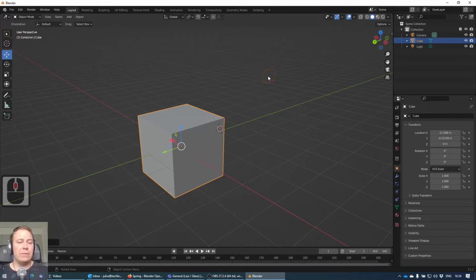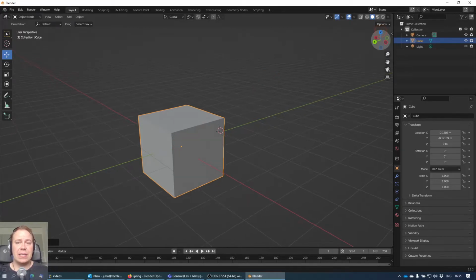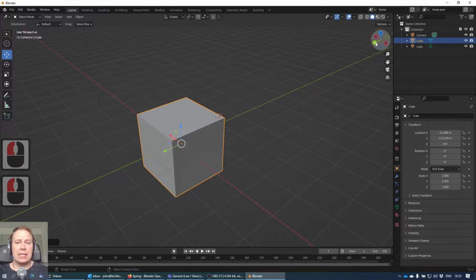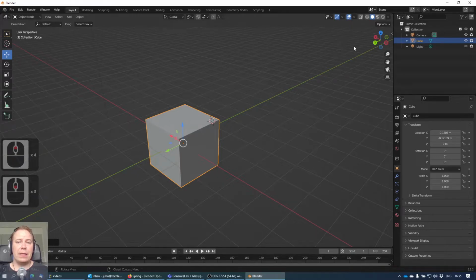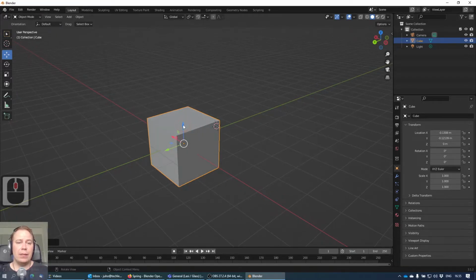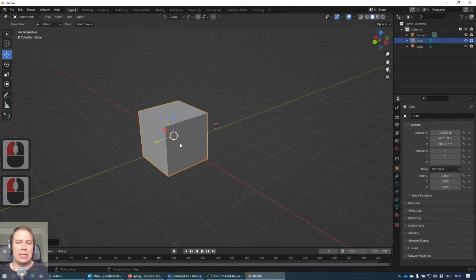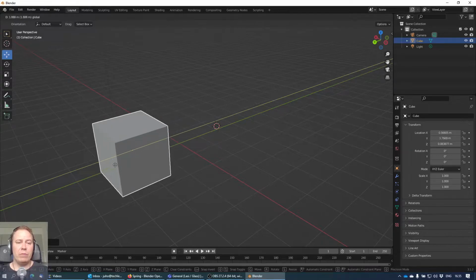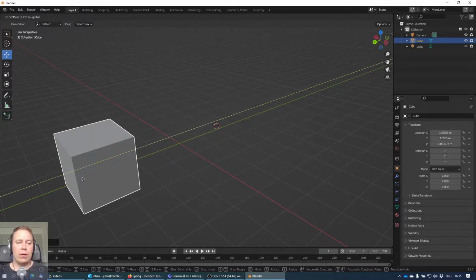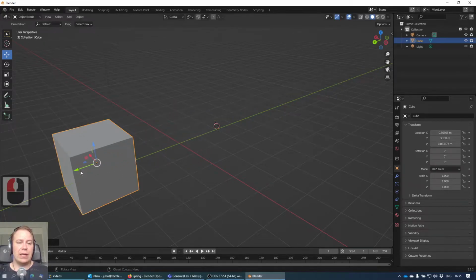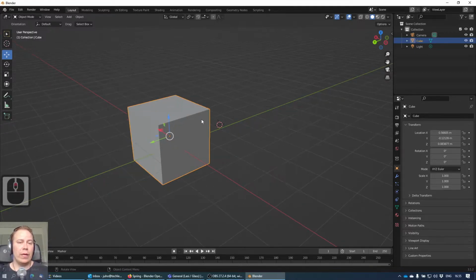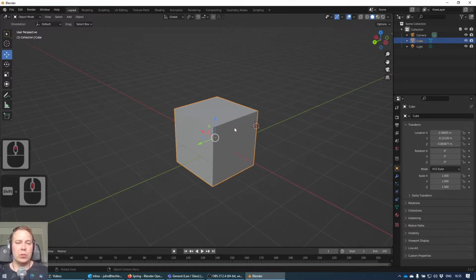And we have three different axes. We have the Z axis here, the X axis here, and the Y axis. Make sure that in Blender the Z axis is pointing up. So you can pull it up using the Z axis, X axis, or Y axis. Remember, if you are moving this and then click the right mouse button, it goes back, and when you release the left mouse button, it stays there. And with Control Z, you can undo whatever you do for 20 times or so, or even more.